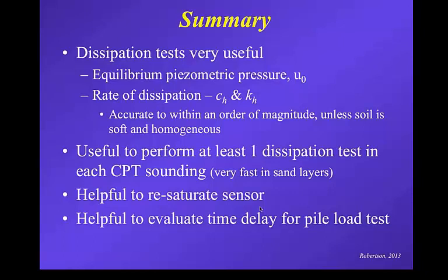And then of course you stop during penetration, record the pore pressure with time, and because it's logarithmic, ideally you want to record relatively frequently at first and then more slowly later on. But often people collect at the same rate, often either every second or every 5 seconds, and so you get a lot of data. And then fix the rods. So don't remove the load during the dissipation. So avoid changing the stresses around the cone by removing the load.